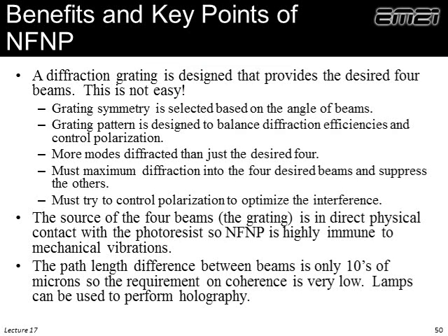Onward. So here are the benefits as I see them of near-field nano patterning. The 2 big ones that stand out in my mind: one is that it's very, very immune to vibration. So in fact, suddenly we can do holographic lithography without really worrying too much about the vibrations. Another neat thing is that since we're using this grating that diffracts the 4 different beams, they really don't separate from each other that far.